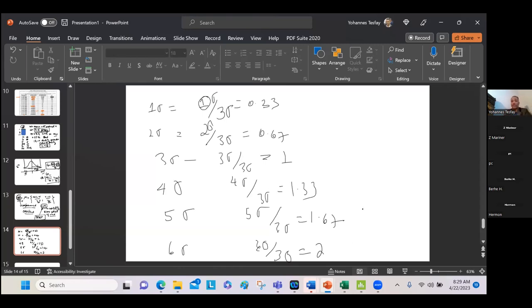So the upper specification and lower specification, just now, for example, minimum of upper specification limit minus target divided by 3 sigma, comma, target minus lower specification limit divided by 3 sigma. That's the formula. So here from the upper end, your upper specification limit goes to how many sigmas? 1 sigma.